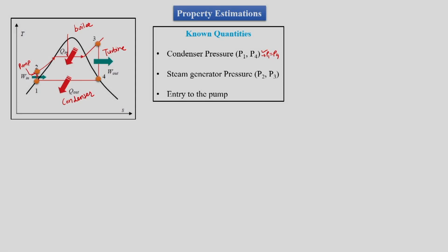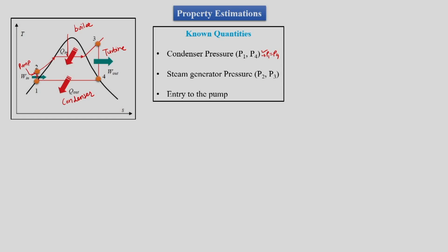In general, in a steam power plant, the condenser is where heat is rejected from the steam, and water in vapor state would get condensed to liquid water. That heat rejection would happen with the use of natural resources like a river or ocean. So atmospheric temperature remains the temperature at which heat would be accepted by the ambience. So this pressure basically corresponds to the saturation pressure corresponding to the atmospheric temperature.